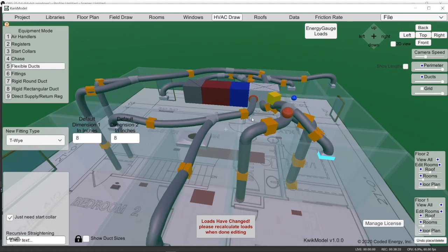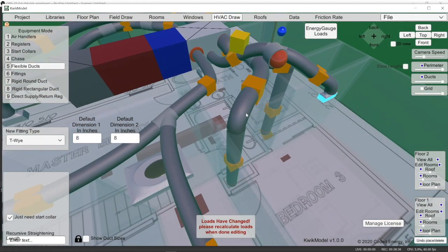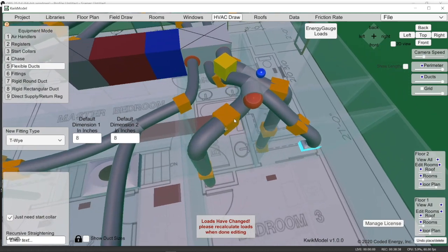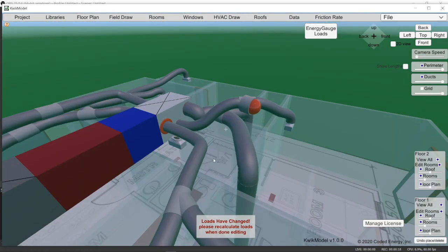And this is kind of funky, and, you know, people complain about this. Oh, you ran your duct so long. It's not ideal, but remember that's an interior room. It hardly needs any air at all. We can go look at the table in a minute. So even if that's a 4-inch duct, that's probably more air than it actually needs because it's an interior room. The only load on this room is the ceiling above it. So it's got conditioned space on 5 sides of it and unconditioned space on 1 side. So I'm not too concerned about that. It looks funny. Doesn't look great, but it is what it is, and it should work fine.